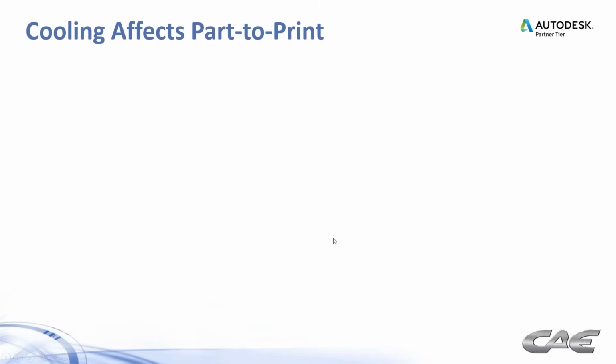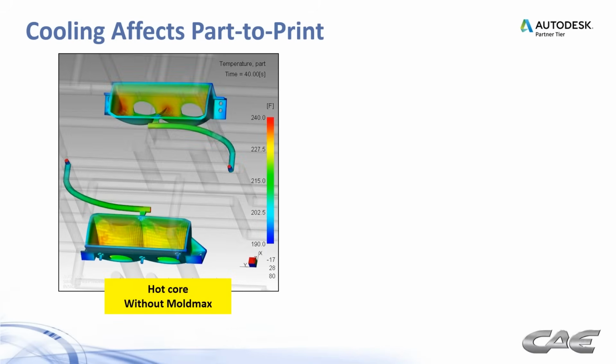So that's gating. That's the first side of the mold design equation. Cooling obviously plays a very big role in warpage as well. Unfortunately, that's often the first area people look to try to solve warpage problems, but it's not necessarily always the best, but it does come into play very often.